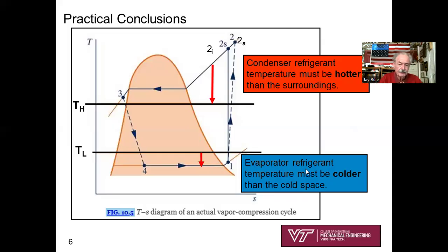And so think about now, change your thinking around a heat pump. What are we trying to do with a heat pump? We're trying to heat the inside of our house. That would be the condenser part. And we're trying to absorb heat from the cold outside. And for a heat pump, that's exactly what we're doing here. And so on cold winter days, you've got to recognize that the refrigerant outside in a heat pump is going to be even colder than the cold outside. And I got to tell you, that blows my mind. But it is an important fact about thermodynamics and these refrigeration cycles.